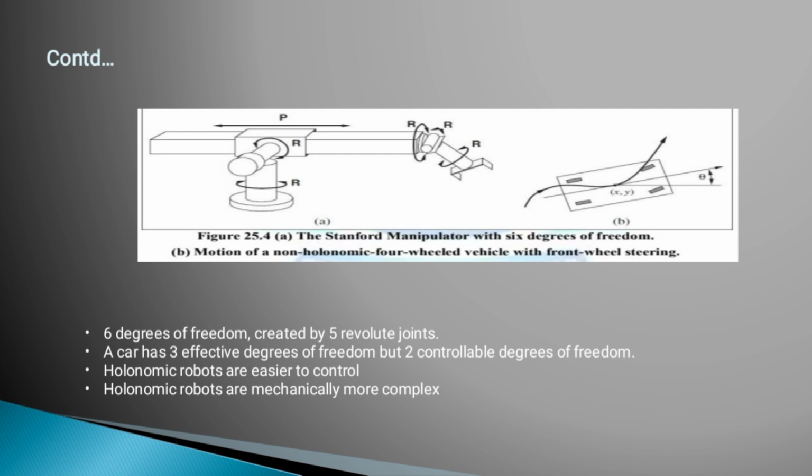The differential drive robot possesses two independently activated wheels that are tracks, one on each side as in a military tank. If both wheels move at the same velocity, the robot moves in a straight line. If they move in opposite directions, the robot turns on the spot. An alternative is the synchronous drive.